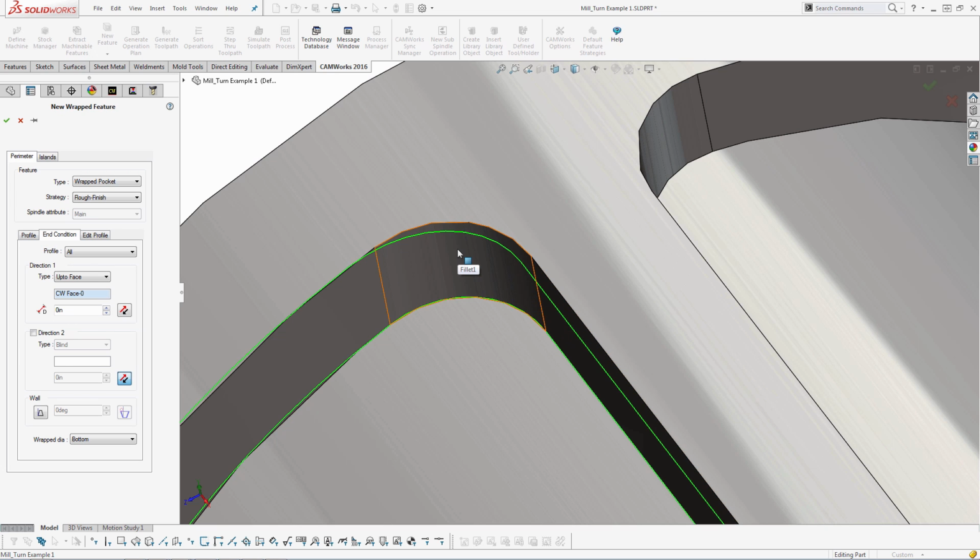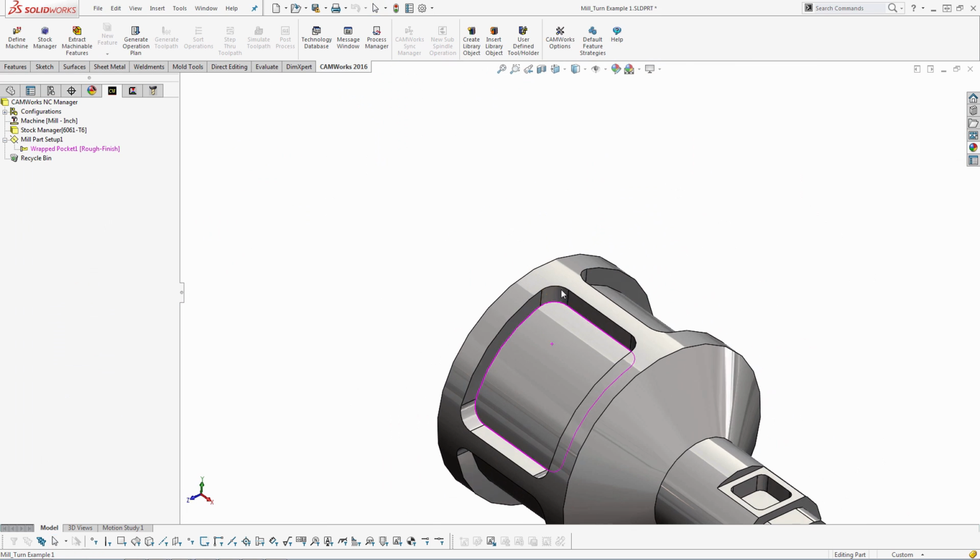If you got a part like this in a drawing and your CAD model and you start programming it and you notice this sort of behavior, you might have to go back to whoever designed it and ask, do I really need to follow this surface directly? If you do, then we're going to have to use the full simultaneous 4-axis multi-axis feature. If they don't, then you can do the simplified feature with the wrap feature. And if they don't, you might want to tell them to draw their parts more accurately next time. So there's my wrap pocket. It's going to behave pretty much exactly like a 2.5 axis pocket.